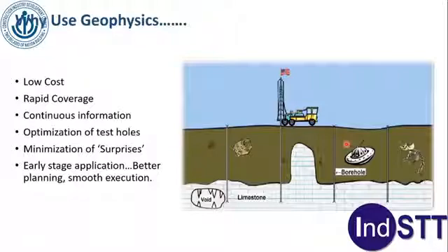It gives you thickness and depth of various layers of various hardness. You know exactly what is the topography of the bedrock, at what depth the rock is. This is elevation, so you can see around 35 meters here. Electrical resistivity imaging also gives you this information.